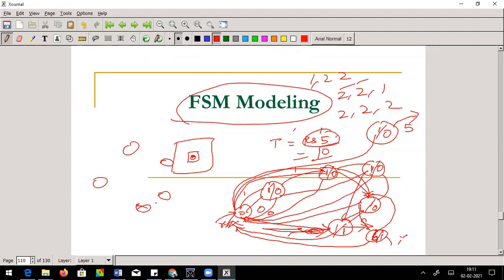This happens not only there. If you consider a simple lift, then you could realize the need for the FSM. Let me assume there are 2 lifts, 15 floors. Now you think about the possible conditions. An entering person can press first floor, second floor, third floor.